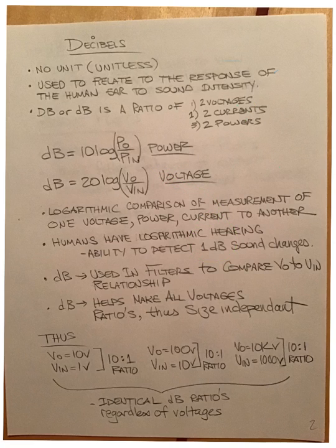We'll build a circuit, feed a frequency in, and feed a voltage peak to peak, maybe 10 volts. The output will always be less than 10 volts peak to peak because we're not building amplifiers in this class.